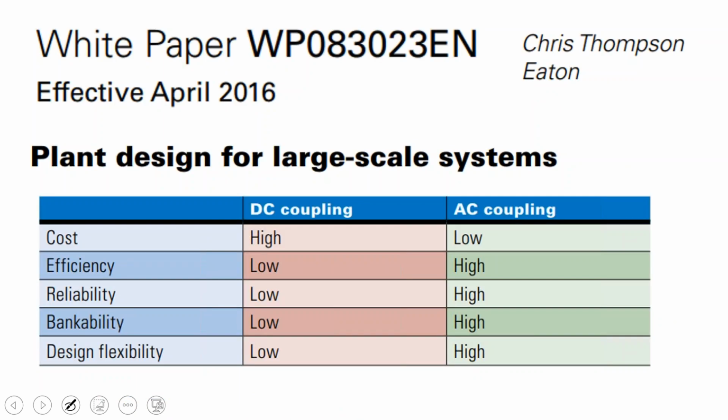So then we get to utility scale, and I don't have any project experience with utility scale batteries. It's still right now kind of a pilot process, but again, utility scale is grid connected, and they want the solar electricity to go into the grid. The batteries are only being used for an hour or two a day to help levelize the ramp up between the solar production going offline and residential evening energy use coming online. They call it the duck curve. And so you're not running the batteries 20 out of 24 hours a day. You're only running the batteries 2 hours a day. So you're primarily dumping all of the electricity into the grid.